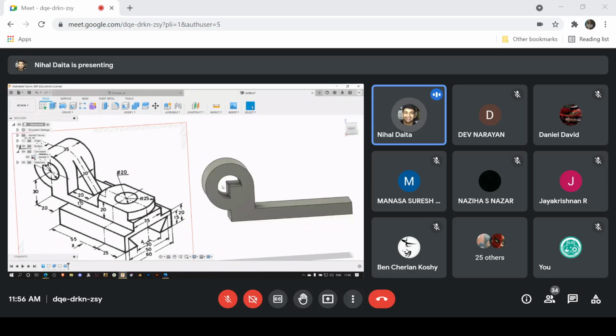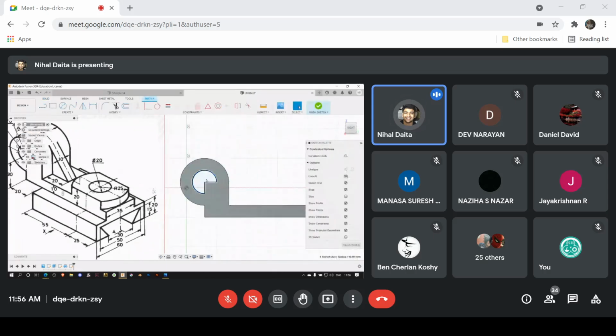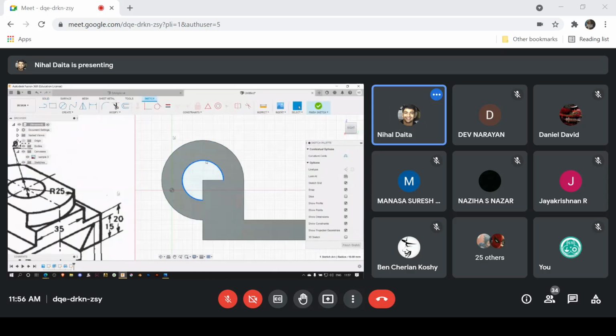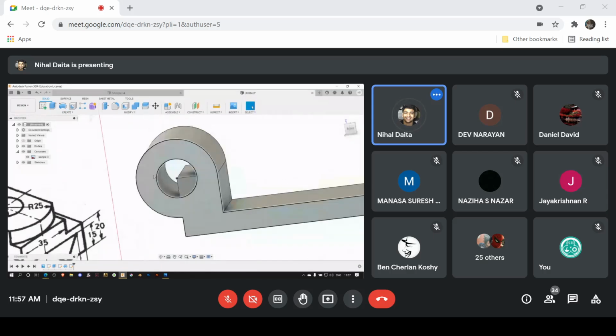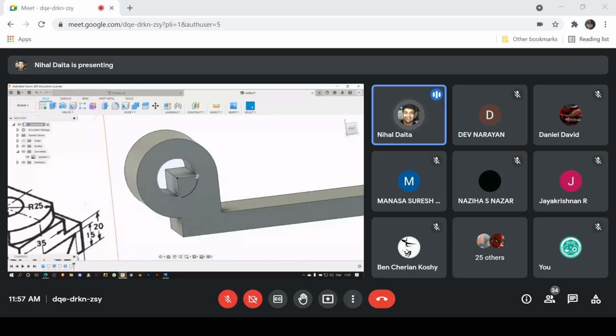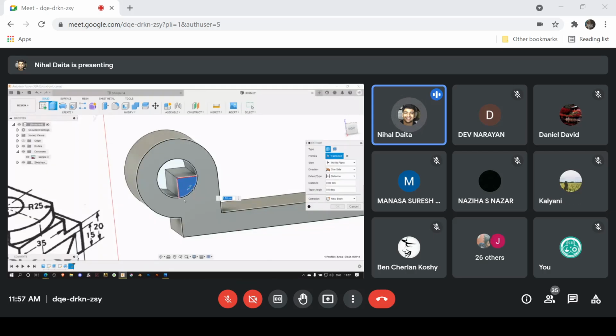Or the extrude cut. So I just choose this surface. I choose to draw on it. I use this circle and I project the circle first, right? I just chose this particular diagram because I can show you most of the tools I explained earlier. So I just got the center point. I just extrude. I just create this, what do you call it? The circle, right? Since I have extra lines, I have a particular sector. I can select it separately. So I can use that to cut. The sector alone can be used to cut it. So I can just drag it and cut it.